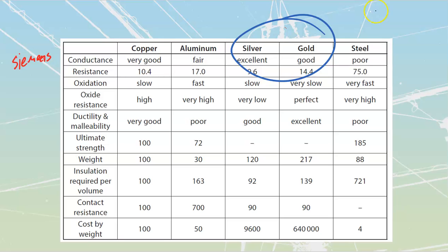If you take a look at copper or aluminum, the way that the oxide eats in, if you've ever seen anything that's rusted, it's pitted, right? We can't have any oxidation. When you've got conductors that are going to be smaller than a human hair, those things cannot have oxidation because it will eat right through that very fine conductor and break the link. So we'll use silver, or we will use gold for those types.